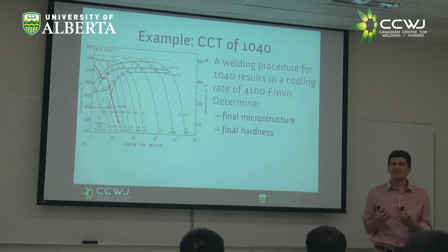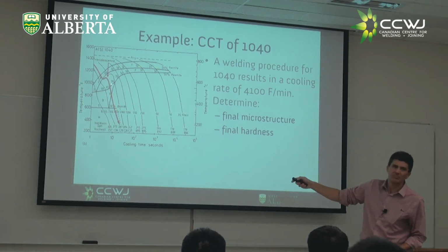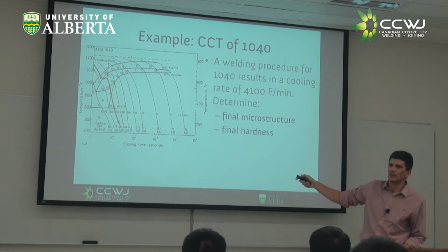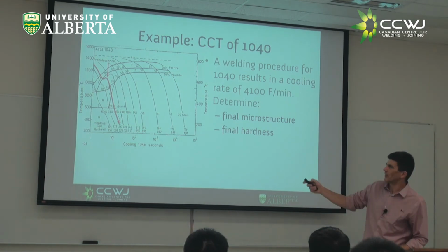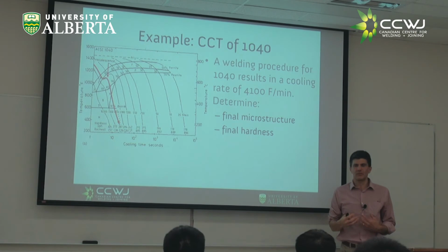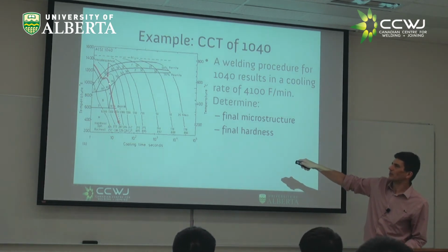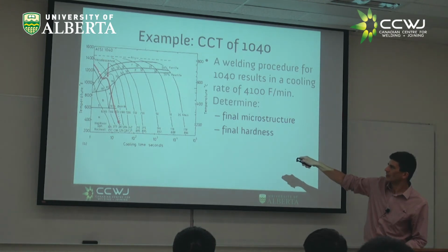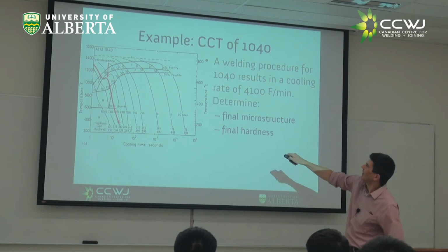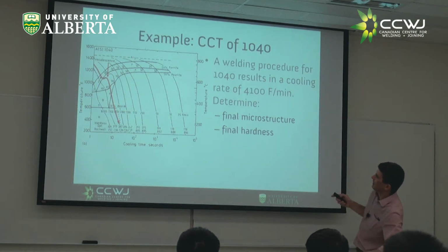And when it releases heat, you see this bump from the internal heating. These curves are experimental curves. With modern equipment, you typically can do a better job. But if you start going too fast, you see this effect called recalescence. So let's forget this bump, which is so important that you can even get a PhD. Let's claim that in reality it goes all down straight, and let's determine for this steel the final microstructure and the final hardness.